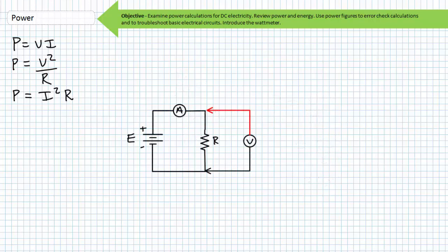Regarding measurement of wattage, ordinarily we have to resort to taking both a voltage measurement and a current measurement, or use one of our other permutations of the power equation to do so. Then we'd have to take these observations and perform some math to arrive at our power value. For example, we'd have to multiply our observed voltage drop across this element by our observed current through this element. You'd have to use your DMM in two different modes and perform some math. There exist, however, special purpose meters designed for single-step measurements of power where no calculation is necessary.